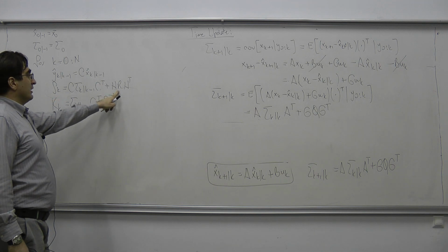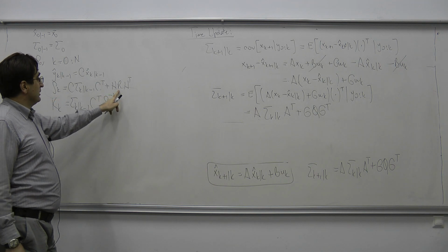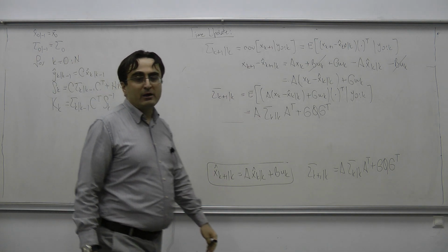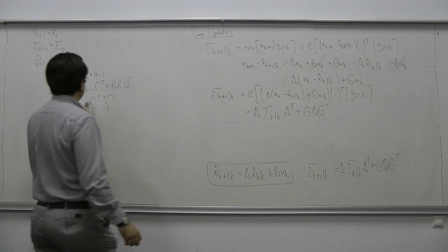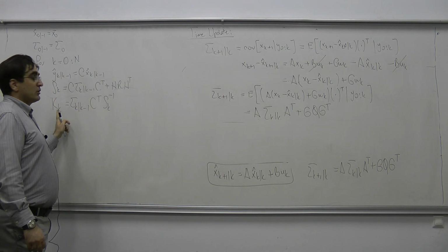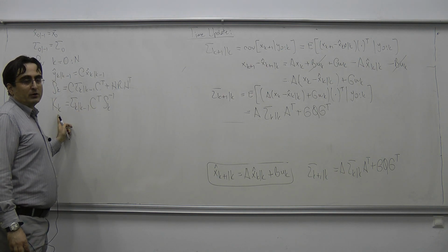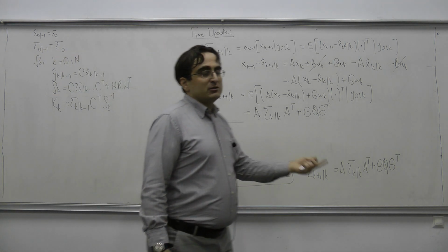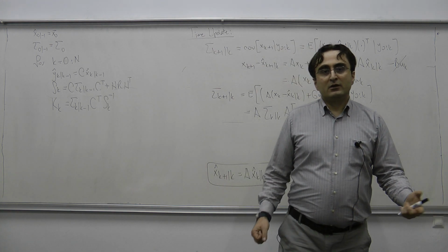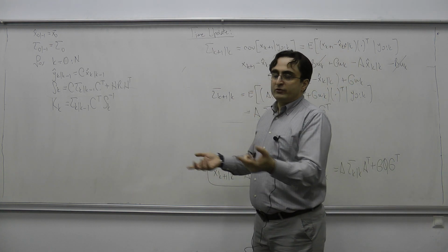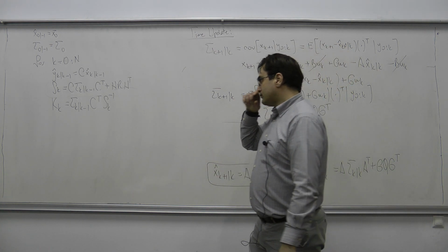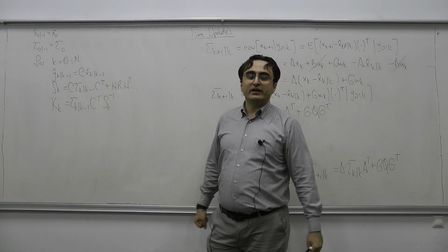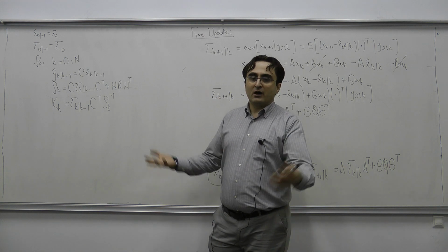So if your measurement covariance R is very, very large, if you have terrible measurement noise, then S_k becomes very large and your Kalman gain becomes very, very small. That means the filter thinks the measurements are very uncertain, so it really shouldn't contaminate its estimates by including the measurements with a large gain.